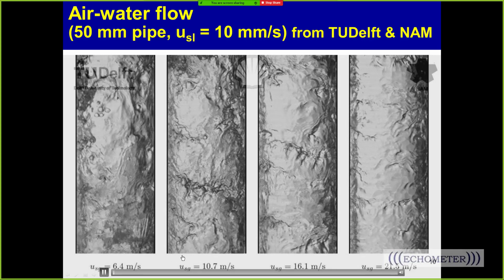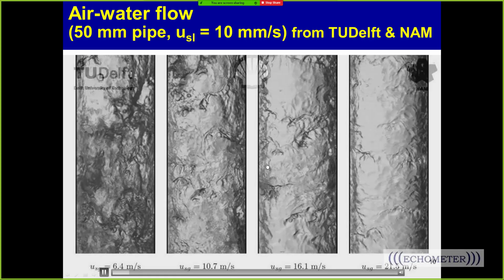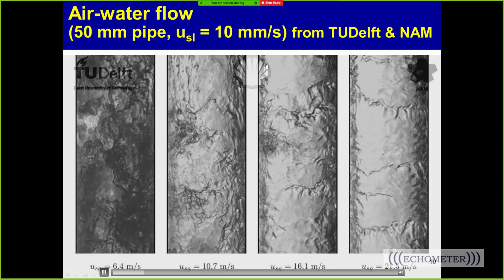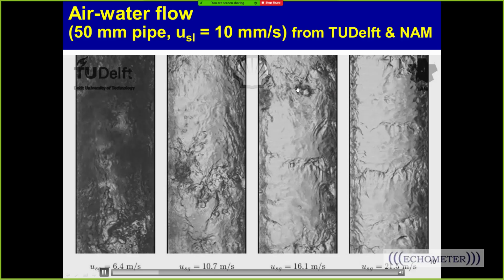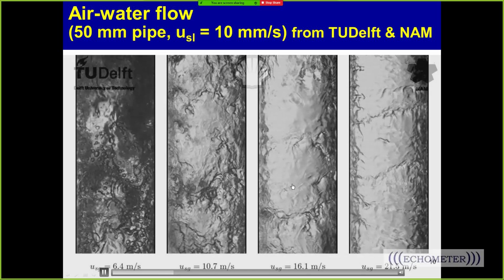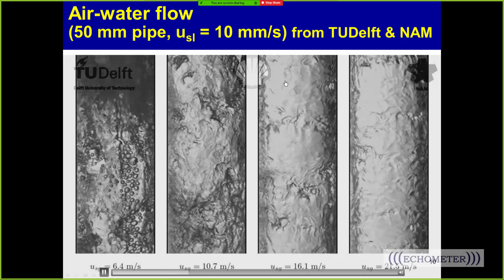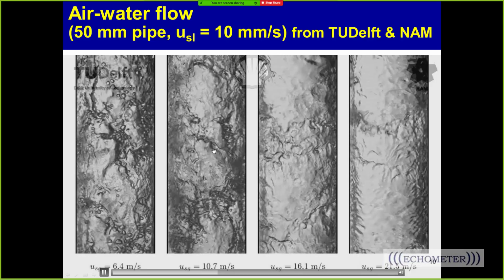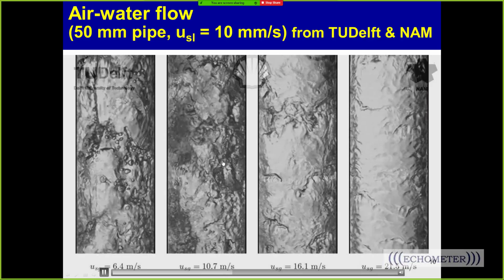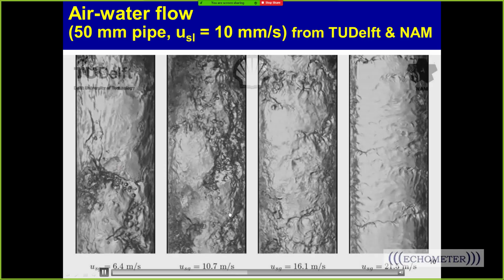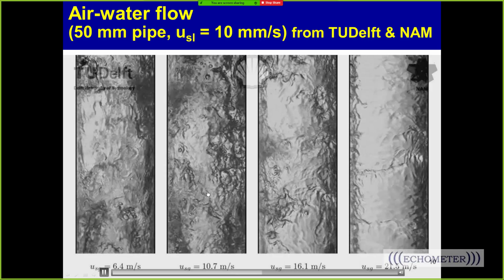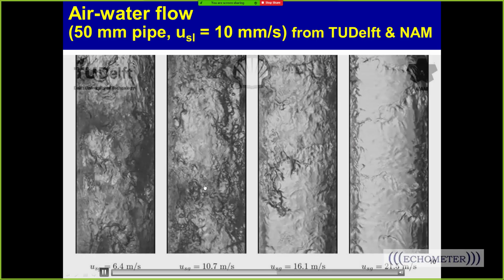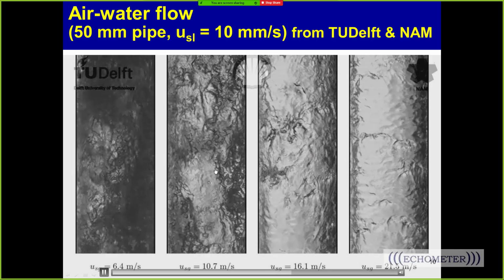Let me start it again. A few droplets are starting to fall off the tubing wall, but they get reabsorbed in the wall, and the velocity of both the film and the gas are still going up. So it's above critical rate. Now here, this is probably the transition, around 10 meters per second. We're starting to see droplets, these big round circles, going down, and it's kind of swirling a little bit, and it looks kind of mixed, and we're starting to liquid load here.